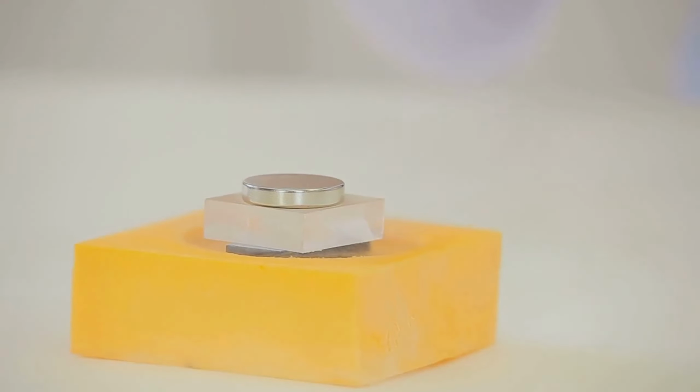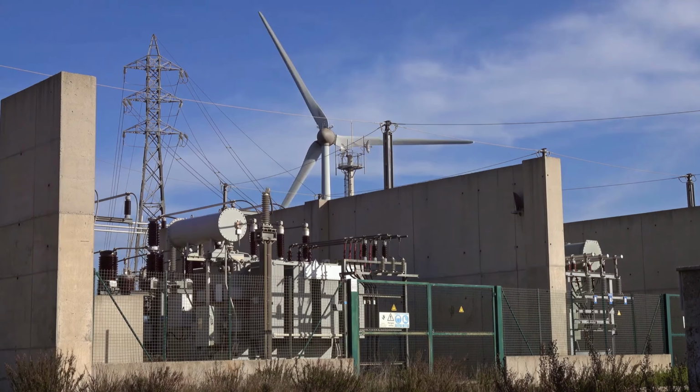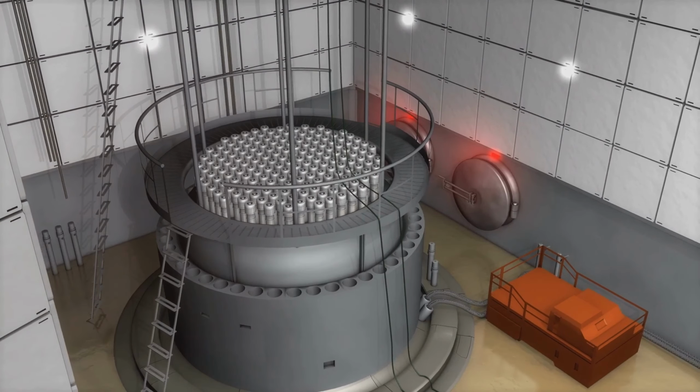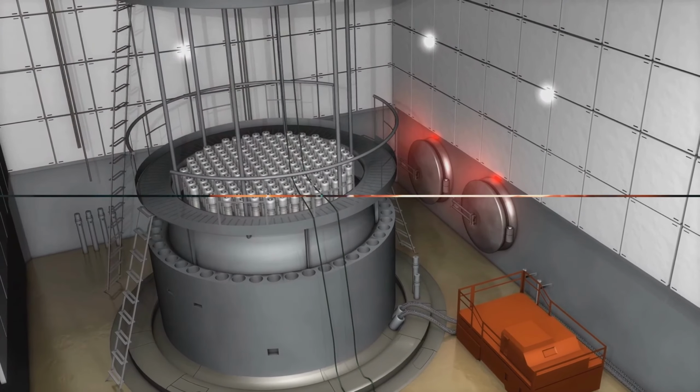The main advantage of MHD generators is their high thermal efficiency, potentially reaching up to 60%. They can be integrated into conventional power plants to increase overall efficiency. However, there are challenges such as electrode material degradation and the need for a high temperature ionized gas source.